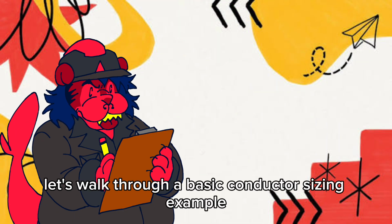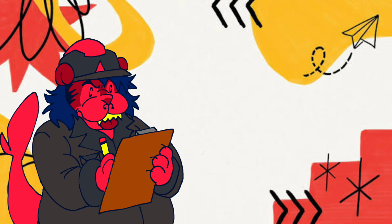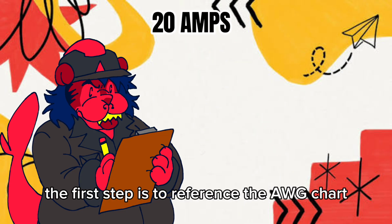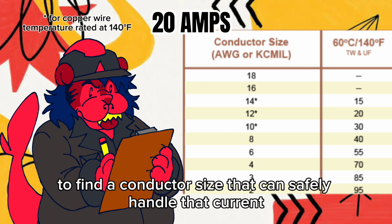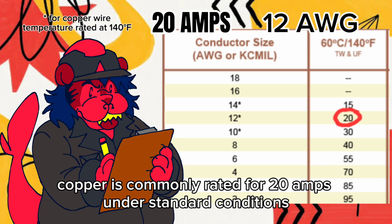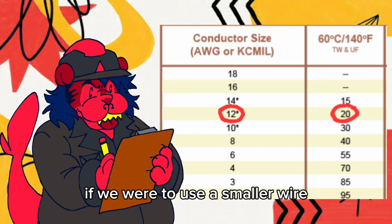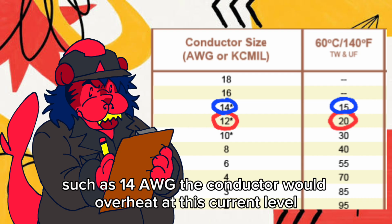Let's walk through a basic conductor sizing example using an American Wire Gauge chart. Suppose we have a circuit that is expected to carry 20 amps. The first step is to reference the AWG chart to find a conductor size that can safely handle that current. Looking at the chart, we can see that 12 AWG copper is commonly rated for 20 amps under standard conditions. If we were to use a smaller wire such as 14 AWG, the conductor would overheat at this current level.